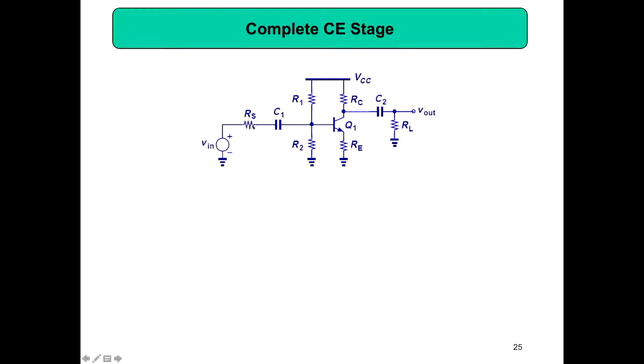So this RS is coming because of the microphone. So you are going to amplify audio signals from a microphone. So you have connected your microphone here. This RS is due to the output impedance of your microphone. Then that signal will be coming, and then here you already got maybe 0.7 volt.